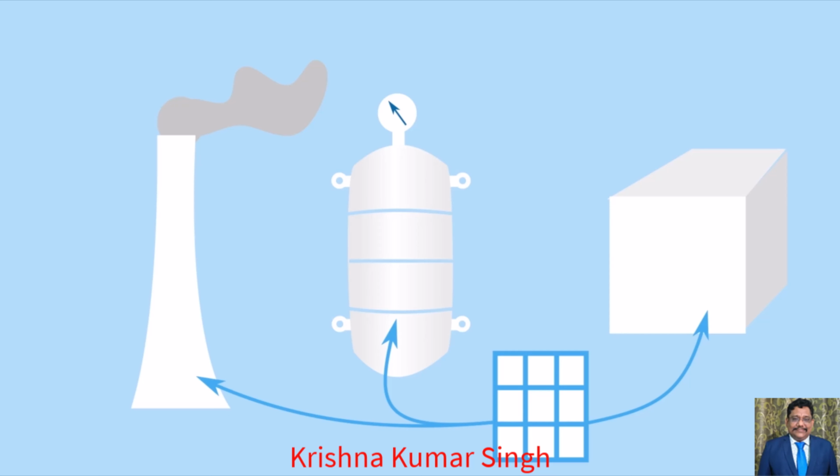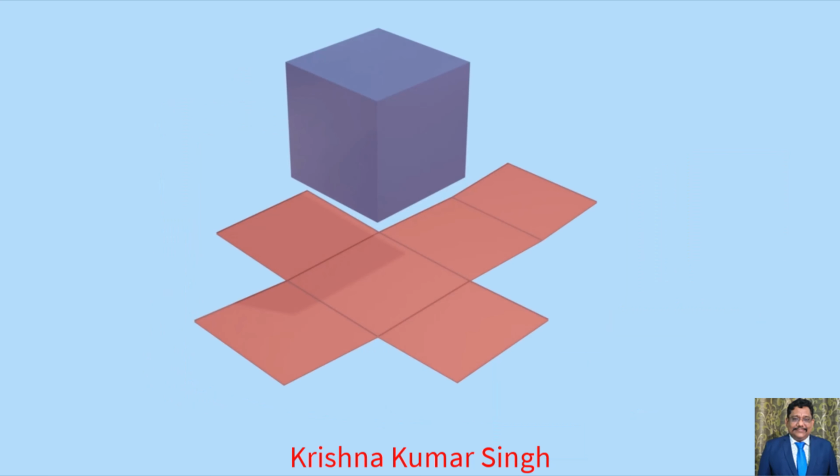Then these sheets are rolled or folded to form the desired shape. This development technique has diverse use, so it's important to study about development or pattern, because patterns can give the true shape and size of each part of the object. Development can give the true area of each surface of the solid.